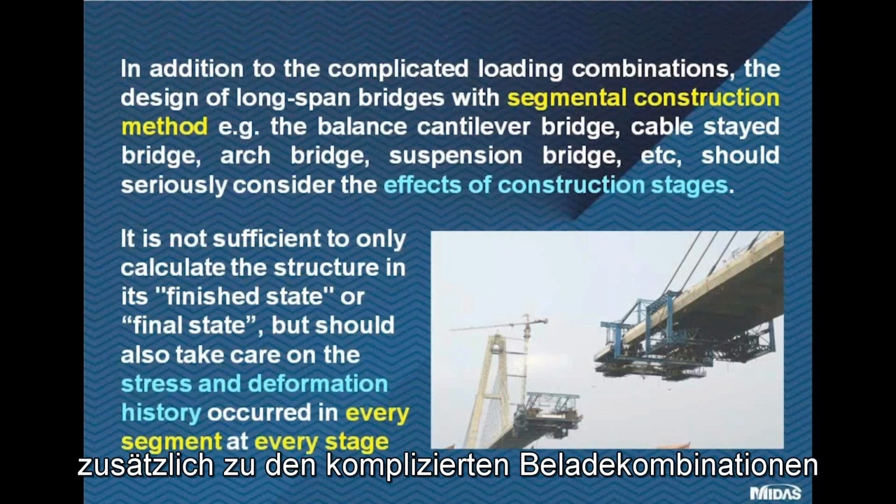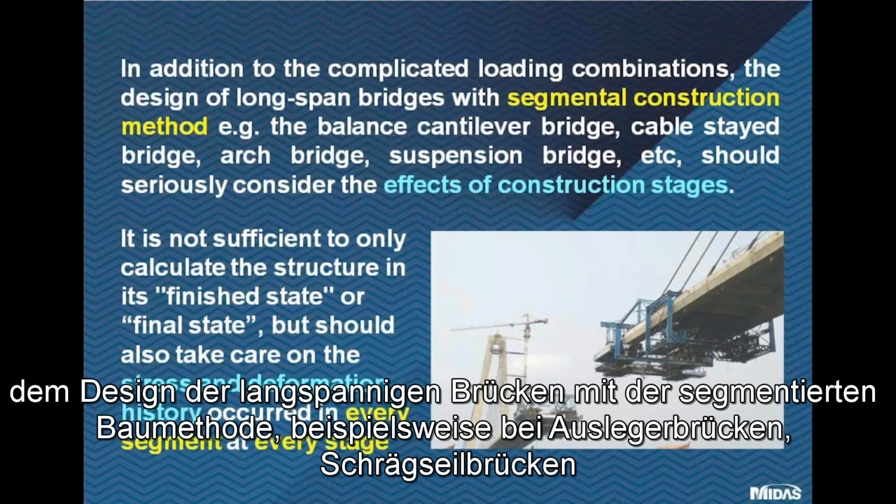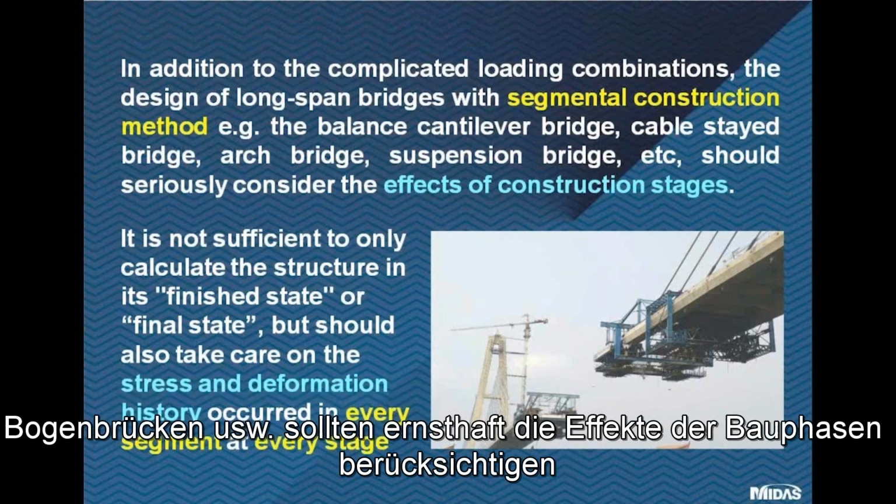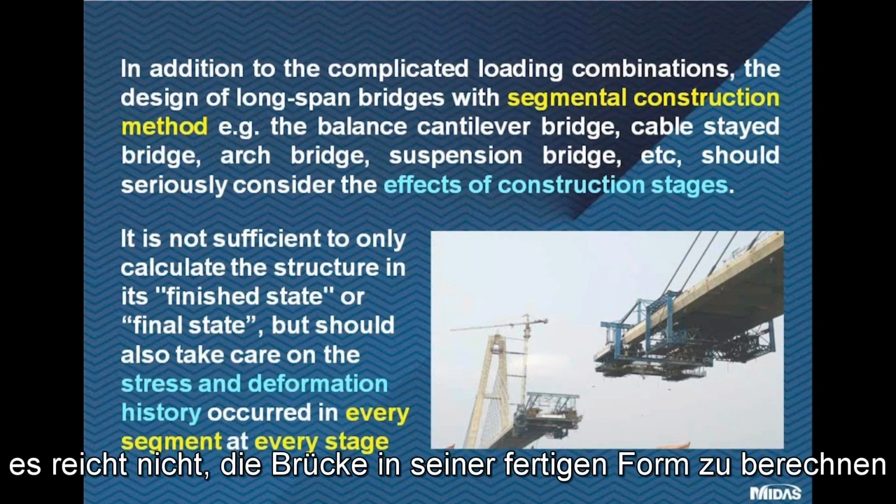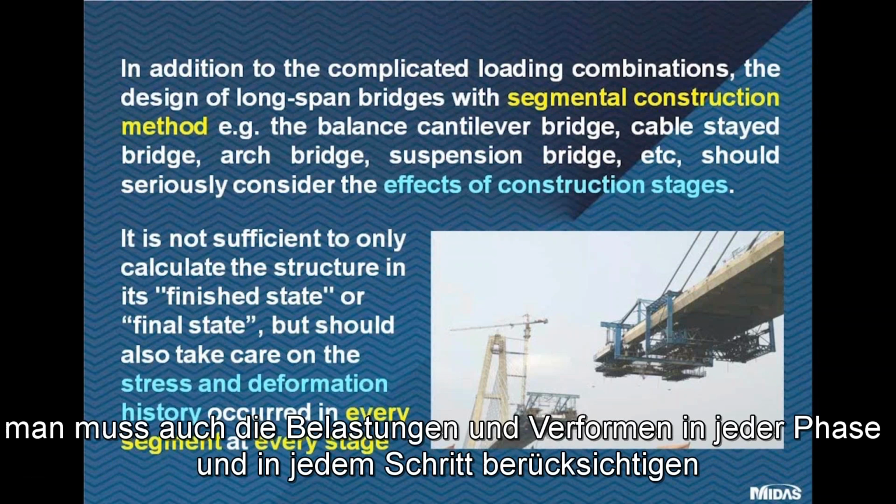In addition to the complicated loading combinations, the design of long span bridges with segmental construction method, for example the balanced cantilever bridge, cable stayed bridge, arch bridge, suspension bridge, etc., should seriously consider the effects of construction stages. It is not sufficient to only calculate the structure in its finished state or final state, but should also take care of the stress and deformation history occurring in every segment at every stage.